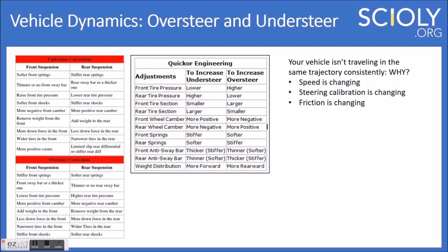Say the first run, immediately after applying the belt conditioner and cleaning the floor, we would see it end up 13 centimeters to the left of the target. Then we'd run it again exactly the same, under the same conditions. We didn't apply belt conditioner a second time because the wheels were still kind of grippy. And we would see it end up maybe 1 centimeter to the left, compared to 13. So it would shift 10 to 12 centimeters just due to the changing friction coefficients of those wheels. They had huge impacts when you're going at those high speeds.